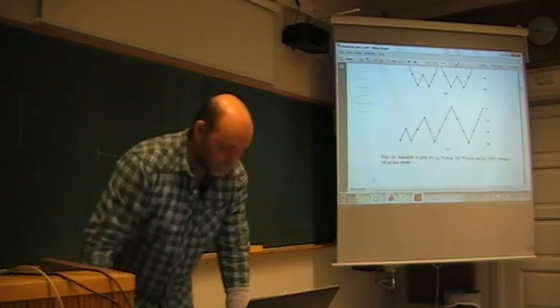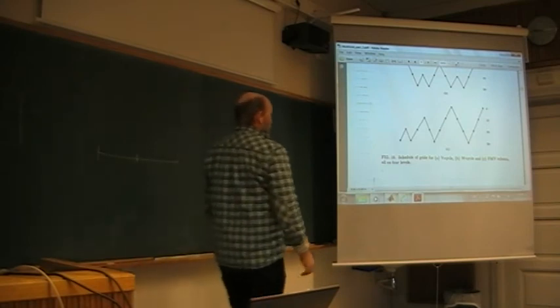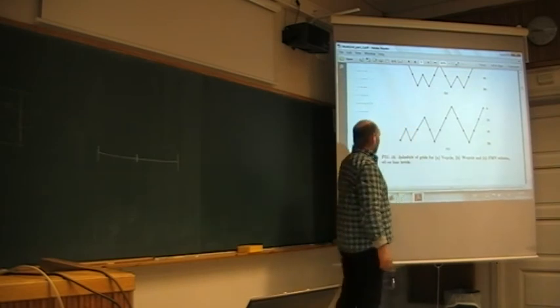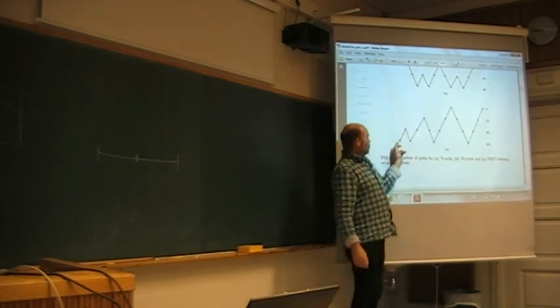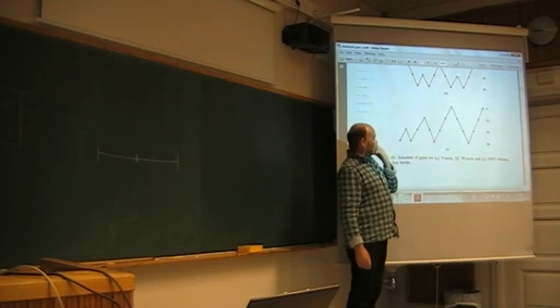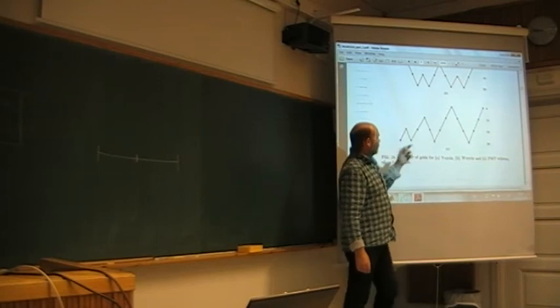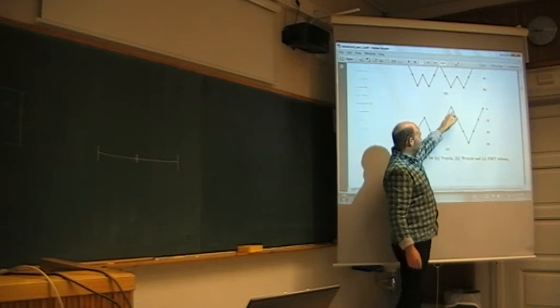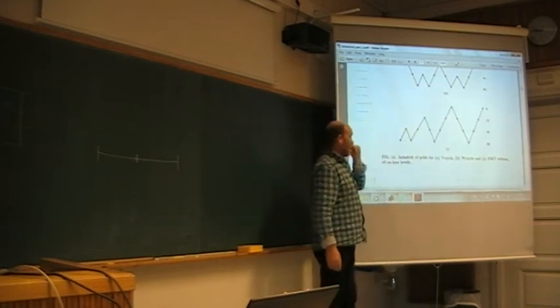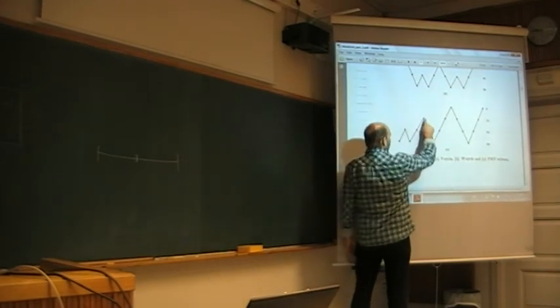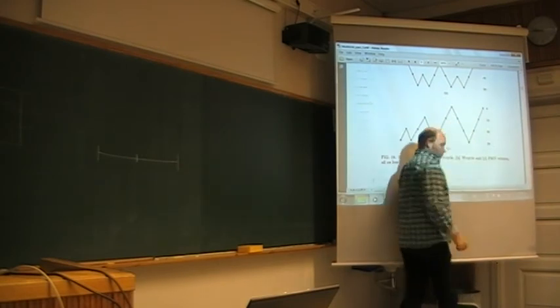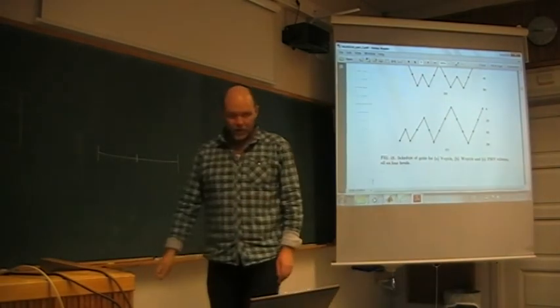But on the bottom here you have a full multi-grid V cycle. That's the initial field which you are otherwise missing. So instead of trying to find an initial field here on the fine mesh, you start on the coarsest mesh. And then you can nest your way up like this. And from here on you will have full normal V cycles. So that would be the normal way.